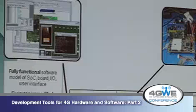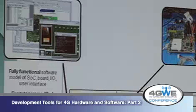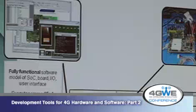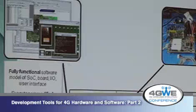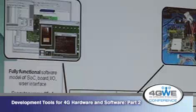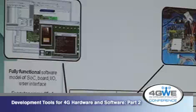So one of the things our industry has started developing is this notion of virtualization for the embedded hardware. Instead of dealing with this nightmare prototype in the lab, we are enabling users to build a fully functional software model. It's actually something I can show you on my machine. I can show you an OMAP 2420 or an OMAP 30 series running as a virtual model on my PC, executing the same code I would beam later on into my actual hardware once it becomes available.